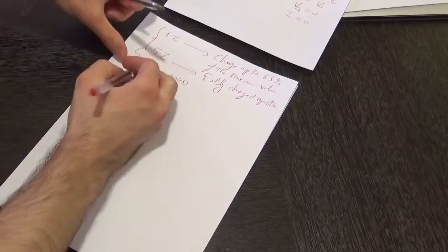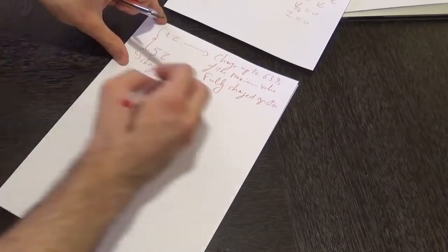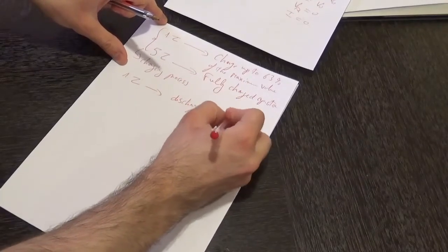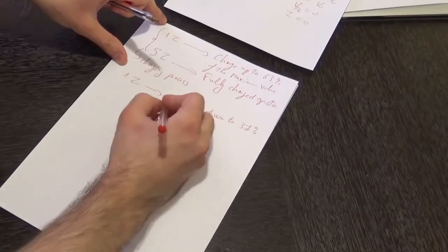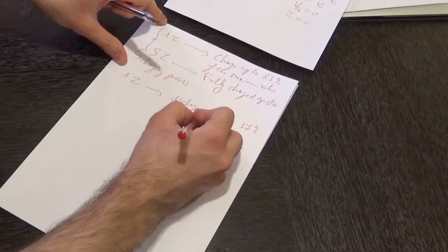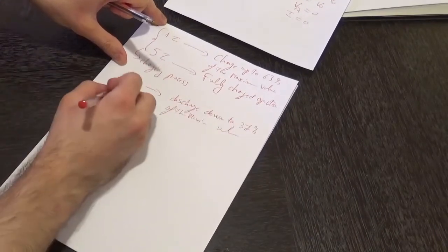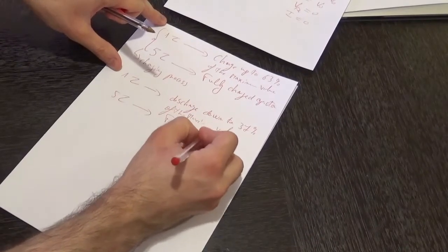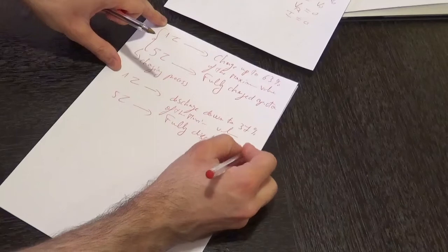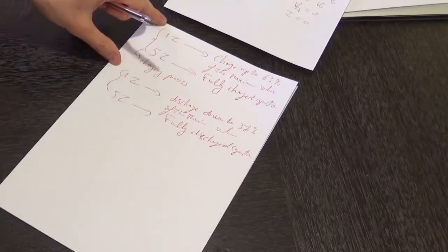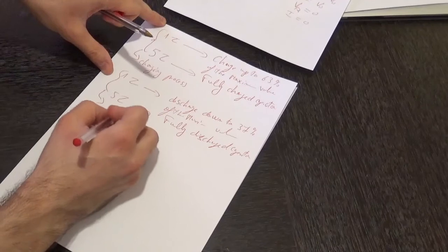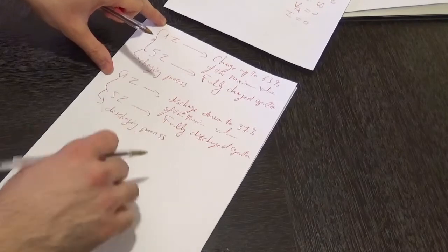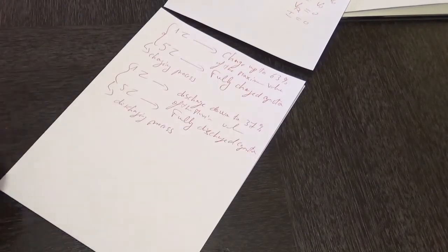Now we can consider another two different time constants, but this time they are for the discharging process. So in that case, 1 tau would correspond to a discharge down to 37% of the maximum value, and then we have 5 tau, which is going to correspond to a fully discharged capacitor. So these two time constants in that case correspond to a discharging process for the capacitor.